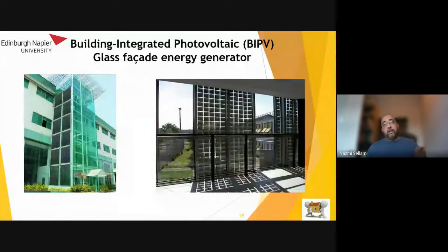The same applied to roofs can be applied to facades. We can see here vertical facades. In the left-hand side picture we see the stairwell, where we used the same principle, and we can actually control the transparency by increasing the gap between the solar cells. But as you can presume, by increasing the gap between the solar cells, we're going to reduce the electricity generated from those PV panels.